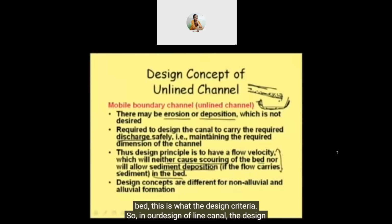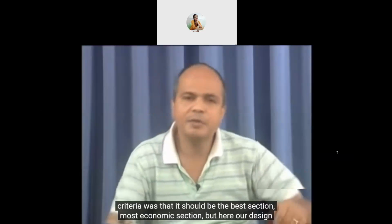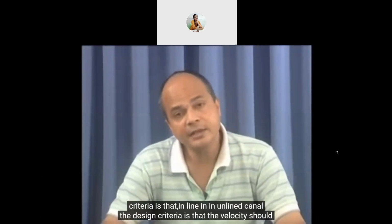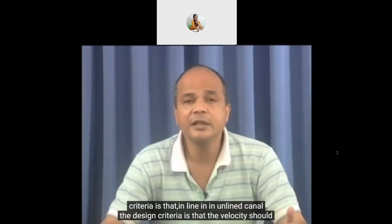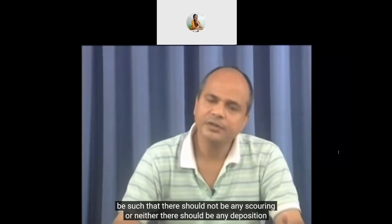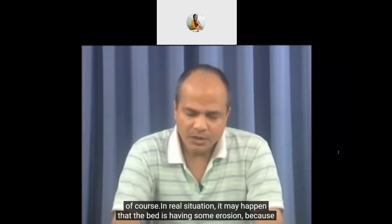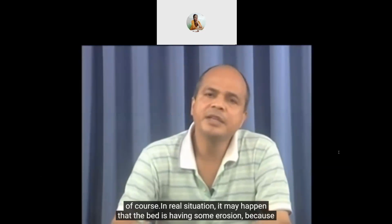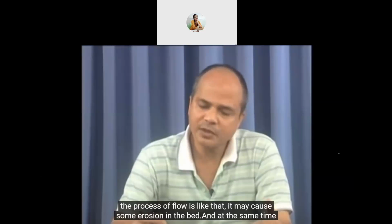So in our design of lined canal, the design criteria was that it should be the best section, the most economic section. But in an unlined canal, the design criteria is that the velocity should be such that there should not be any scouring, neither any deposition. Of course, in real situations, it may happen that the bed has some erosion, because the process of flow is like that.